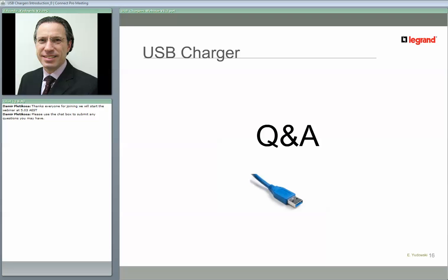There is another question that finally arrived. If we have to extend the 5 volt cable, what is the maximum distance? That is a very good question. We are already extending the cable on the 5 volt side, and we did some measurements, and we are able to confirm that the 5 volt cable can be extended up to 1.5 meters from my recollection. But obviously there is a small degradation in the charging capacity due to losses in the cable itself, but it's very, very minimal.